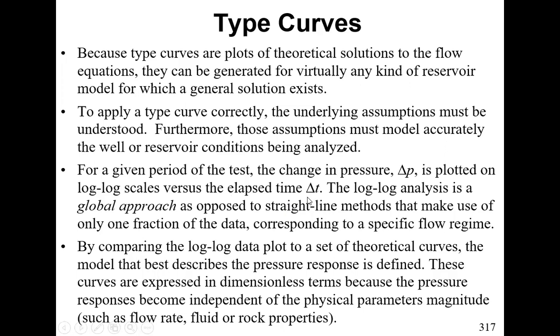So you see, we've moved from the plot of pressure against the log of time on the semi-log graph, and now we're talking about the log-log scale. The log-log analysis is a global approach as opposed to the straight line methods.